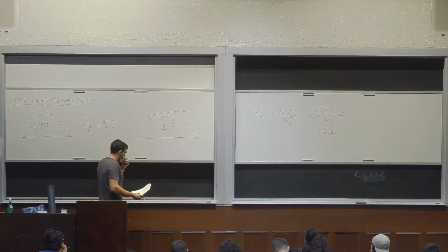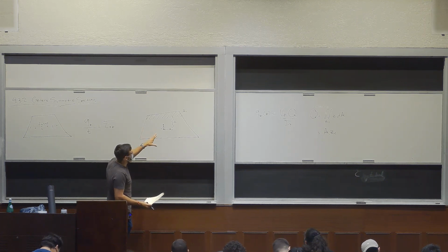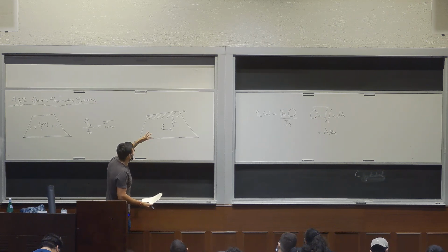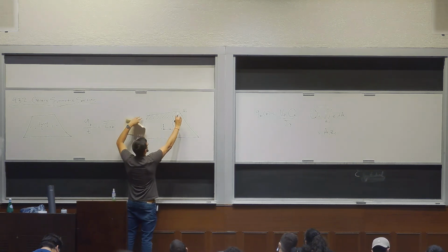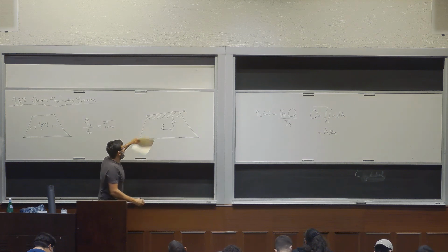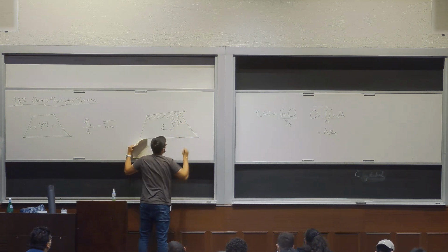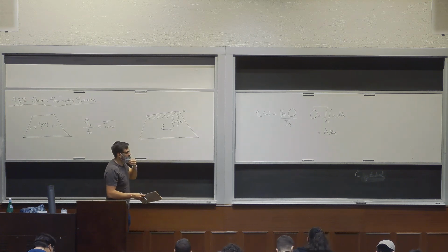And to find Q, we would multiply that area 1, in meters squared, times the z position of the centroid of that area. So we have this other shape here. It has its own centroid, which will have a different z value, zc, and that's what I've drawn there.